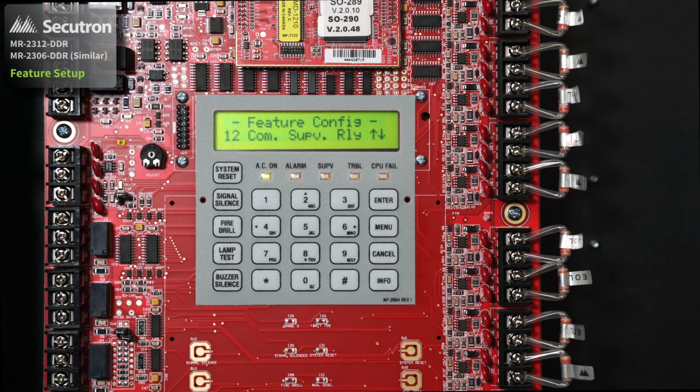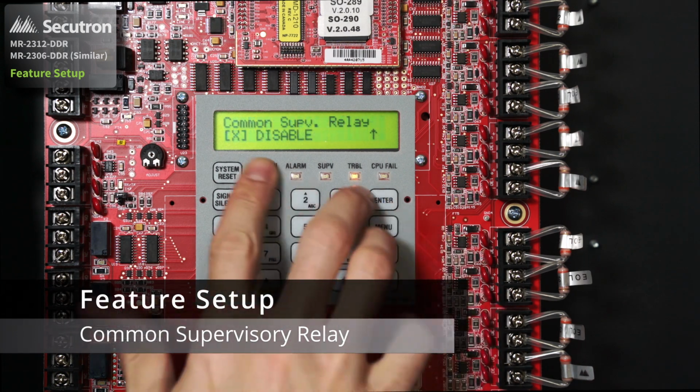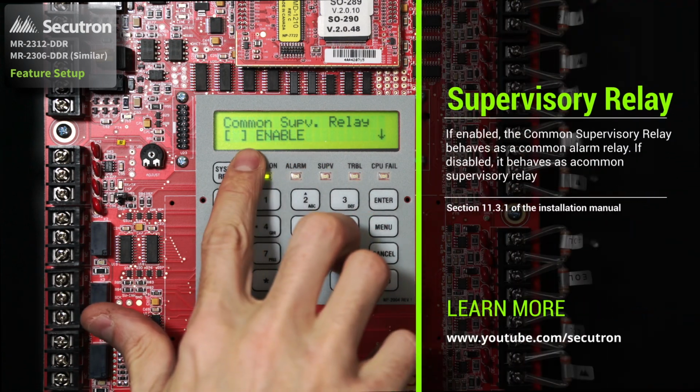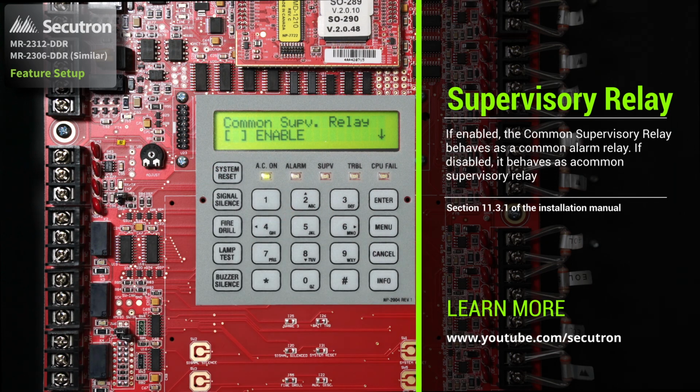The next feature is the common supervisory relay. We select enter. By default, we see that it's been disabled. If we would like to enable it, we can hit the up cursor and hit the left or right arrows to enable the common supervisory relay. If enabled, the common supervisory relay behaves as a common alarm relay. If disabled, it behaves as a common supervisory relay.